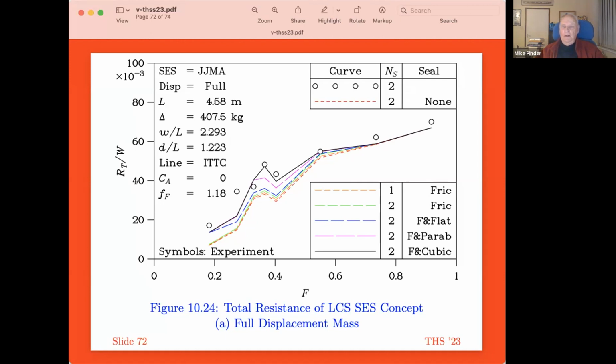I had a little problem on the largest craft, which is the Skimmer 12, of lateral stability. And I'd like to thank Malcolm for inventing his skirt shift system, which helped a great deal in trimming the craft and also coping with side winds and off-center loads. And that helped a lot.